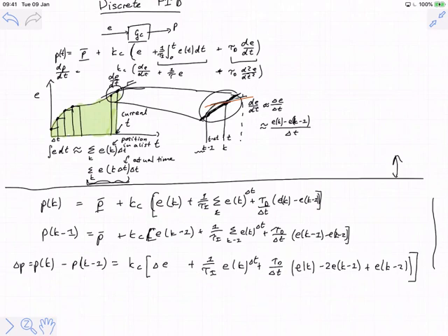It is not correct to imagine that a discrete controller or that a velocity form controller is an approximation or any kind of derivative form of a position form controller. It is the same controller expressed differently. I want to make that very clear. Given the same system, given the same error signal, a velocity form controller and a position form controller will calculate identical output values.